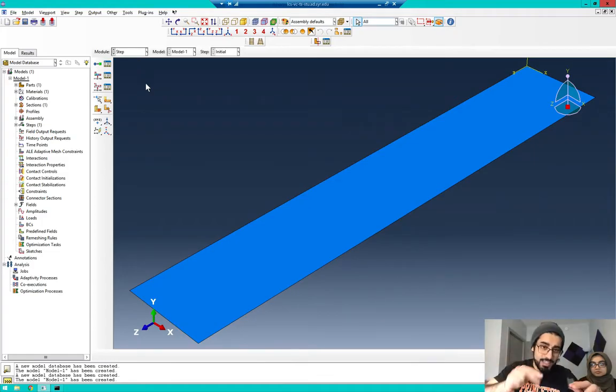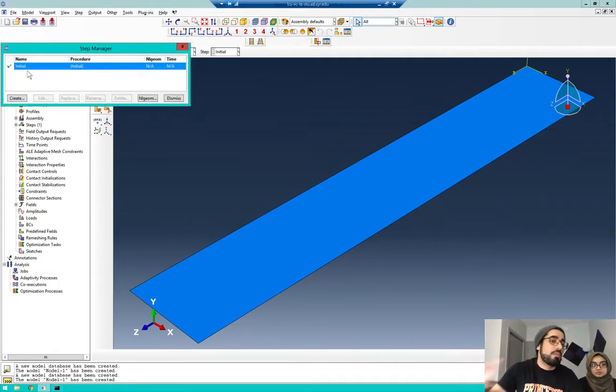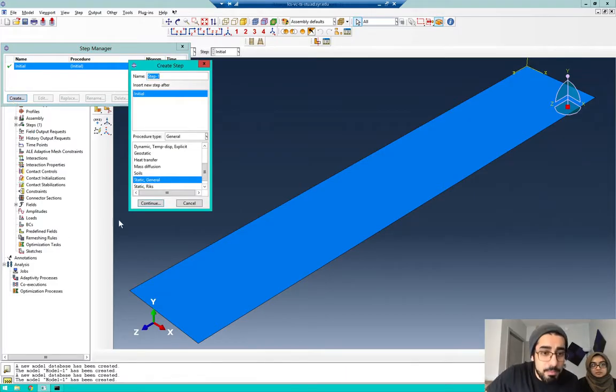And then later, I applied the load to it. So in the initial stage, there was nothing, right? Just the boundary condition here. I'm gonna tell Abaqus that someone was holding the ruler from here, which is the table. And in the next stage, we came and put the oranges here. So how many stages do we have? Two stages, yes. The initial stage is always there by default. I'm gonna create a new step here.